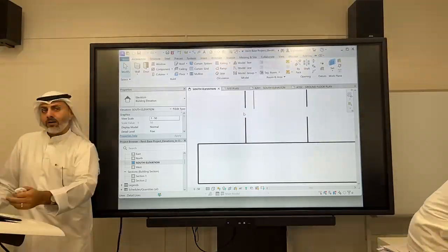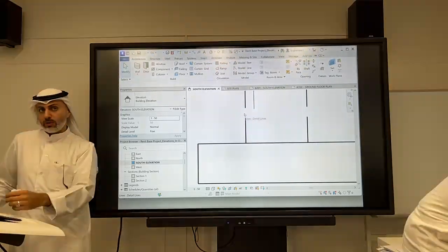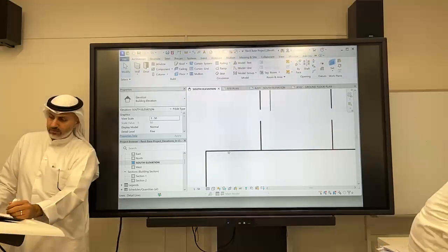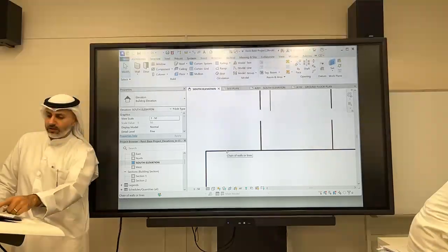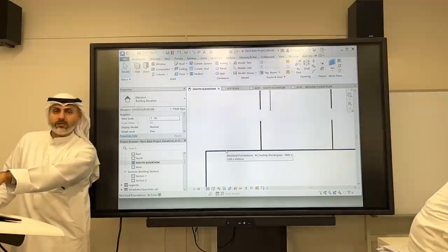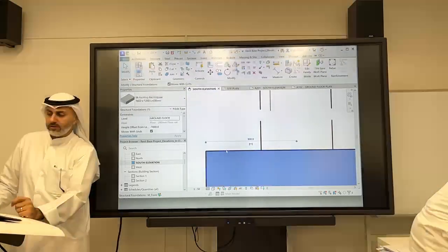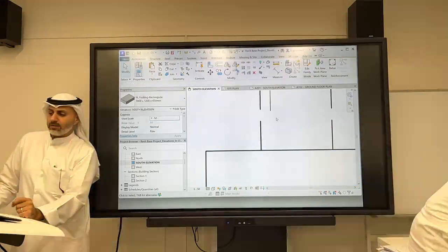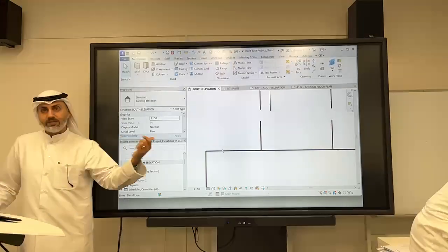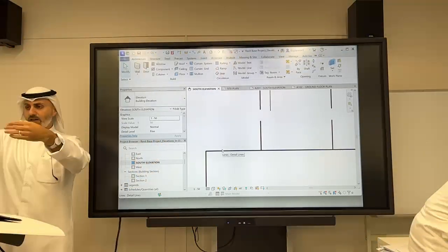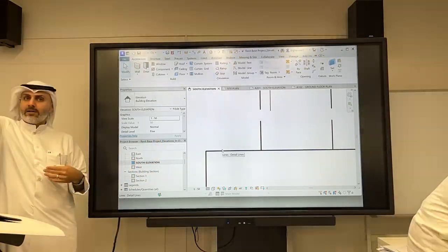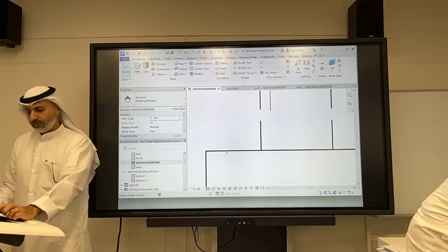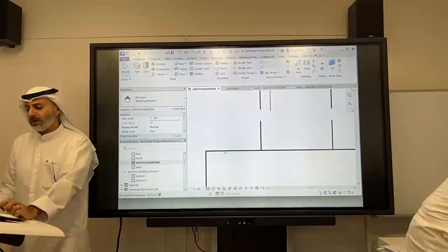Now I want to remove the column and remove the footing, the actual model. I want to hide it. So I go over the line and then you click Tab till it selects structural foundation or column. You click on it and then you right click, hide in view element. After you hide it, if it's still showing, there's probably one behind it. So I do the same step and I hide it. In some views, you might have to do it 3 times actually.